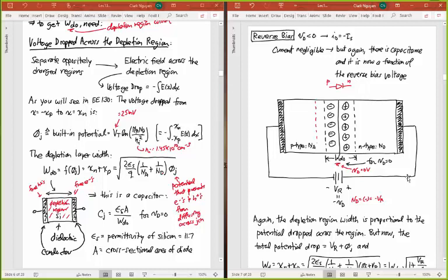And the way that it adjusts is to create more static charge. And the way that it creates more static charge is to push electrons out of this N-type region, to create a depletion region, and on the P side to push holes out of this region. And when we do that, we create more charge. So you can think of them either as holes and electrons sort of combining more there, or electrons being pushed out of this. And this is the more correct way to think about this. You're pushing the electrons and holes out, and what they do is they go out here and they recombine right there. So they recombine and destroy each other out there.